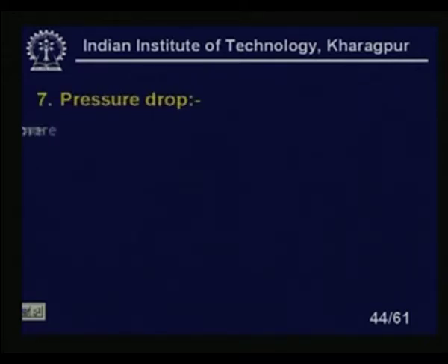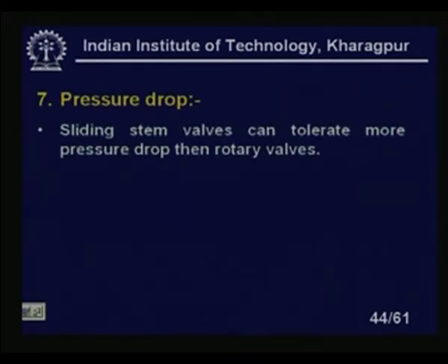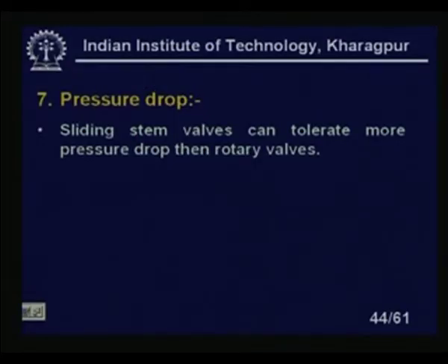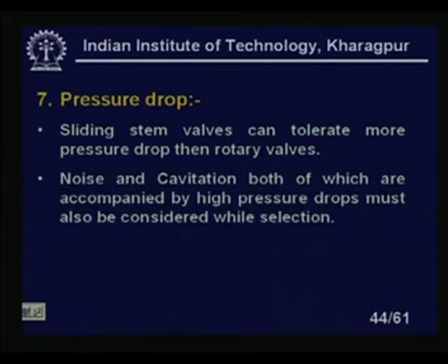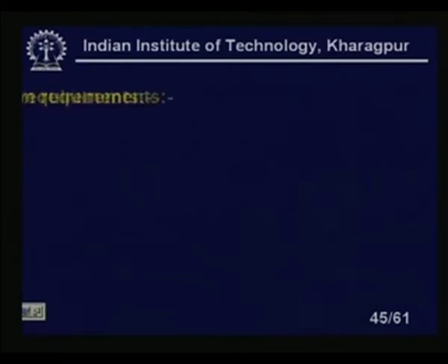Pressure drop, this is another important thing, the pressure drop across the valve. Sliding stem valves can tolerate more pressure drop than the rotary valves. Noise and cavitation, both of which are accompanied by high pressure drop, must also be considered during selection.